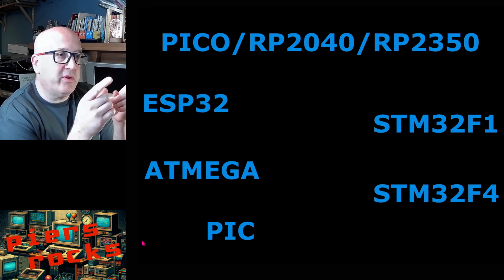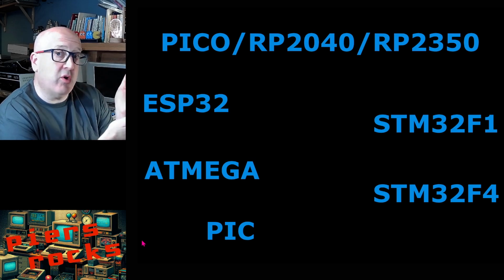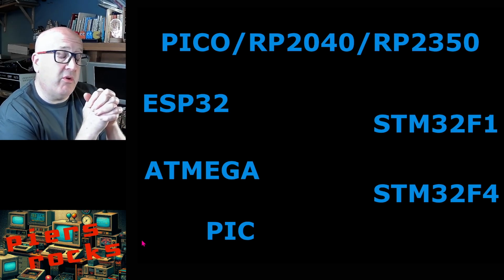And then really importantly, the STM32F1 has actually quite a poor selection of 5-volt tolerant GPIOs for this application. It has enough if you go with the 64-pin variant, which is what I've gone with for the STM32F4, but they're not in the right locations. And I'll explain that a bit more when we start looking at the schematic.